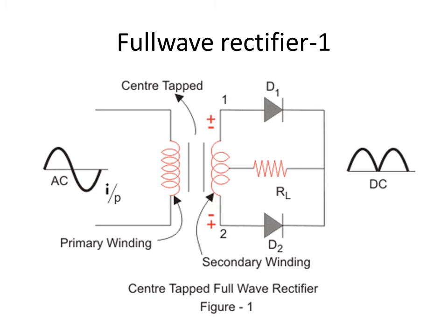So essentially we don't have any rectification. Whatever input is there, exactly the same thing will be appearing at the output also. So that is not a successful rectifier. You have to be careful in the way in which you are going to connect the load resistance, by making sure that the current will flow along the same direction through RL, both during the positive cycle and the negative cycle of the input. Then only we'll be having rectified output.